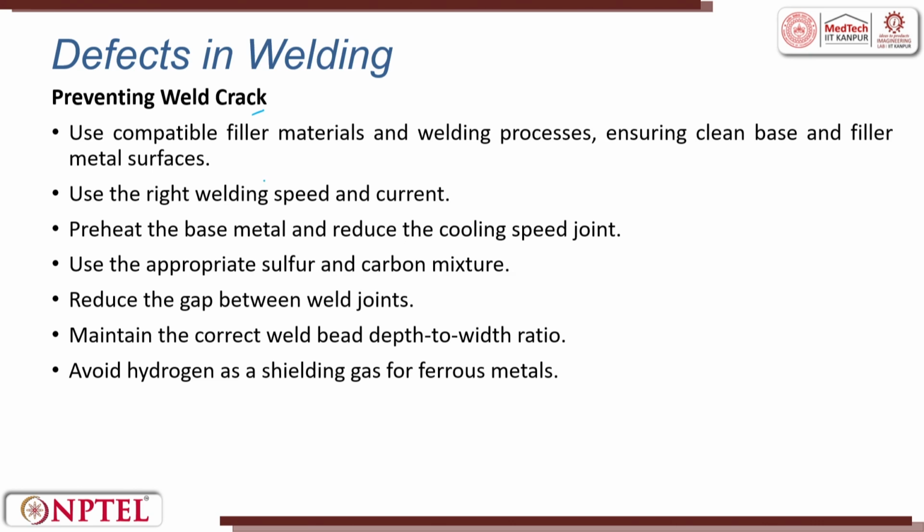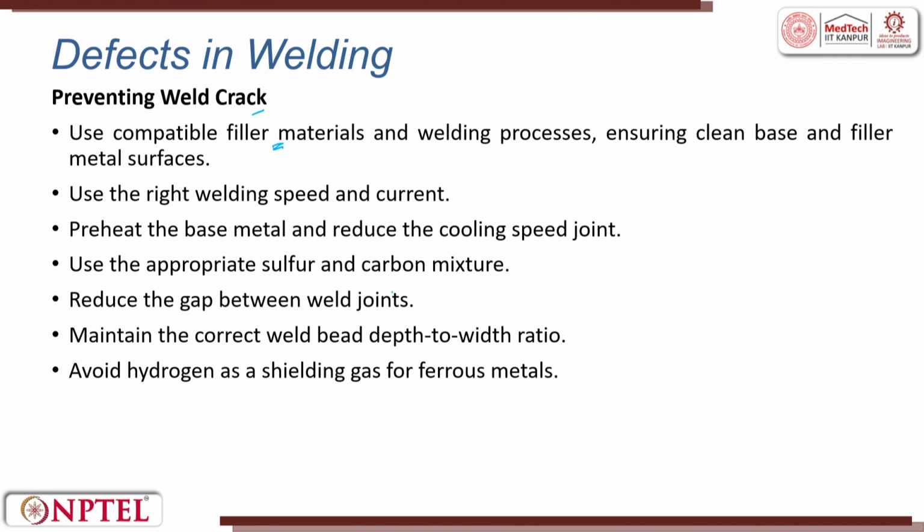For prevention of these weld cracks, you have to use a proper compatible filler. Whatever filler you use, if it solidifies faster, it gets attached to the base material, then improper welding happens and there will be a crack. So we have to find a compatibility in which the viscosity of the liquid which flows comes in contact. When it contracts, it also tries to take the base material along with it. It will not be shrinking so much, but taking them along. So use compatible filler material and weld process, ensuring a clean base.